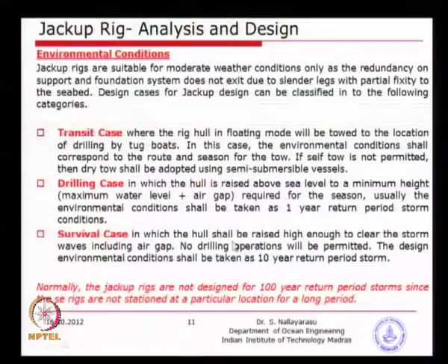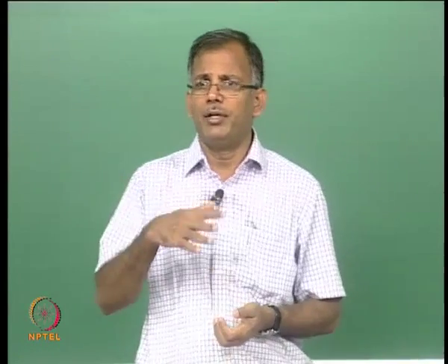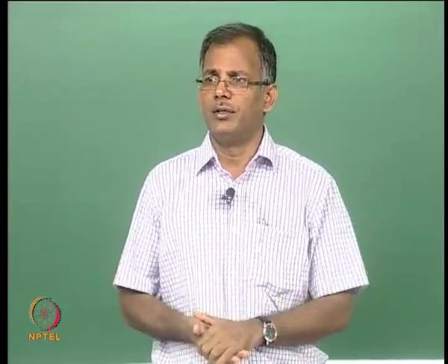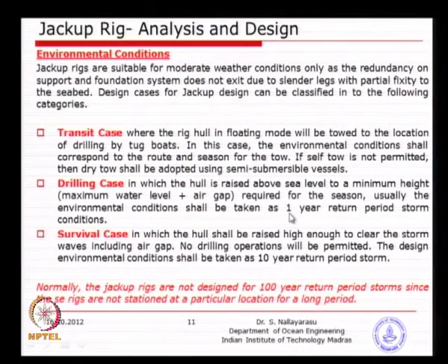So, depending on that, if it is going to be a substantial period, you may actually select 1 year return period. That means the maximum sea state that is going to occur during a 1 year return period you will select and then design. Suppose you want to station it longer, you may actually select 10 year. Suppose your rig is going to be there for 2 years, normally not required, because most well platforms have 10 wells, 15 wells, and each well could be drilled in 15 days. You are not going to stay there for a very long period. So, typically the drilling case is a 1 year return period wave.